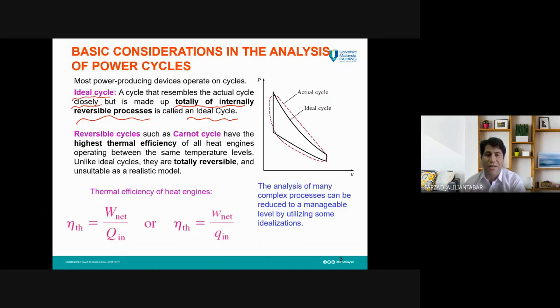We may also have leakage of thermal energy. So we may not have a constant temperature or even an adiabatic system, because we cannot generally have 100% isolated equipment. So we will have a leakage of thermal energy, which is one of the irreversibilities of the process.